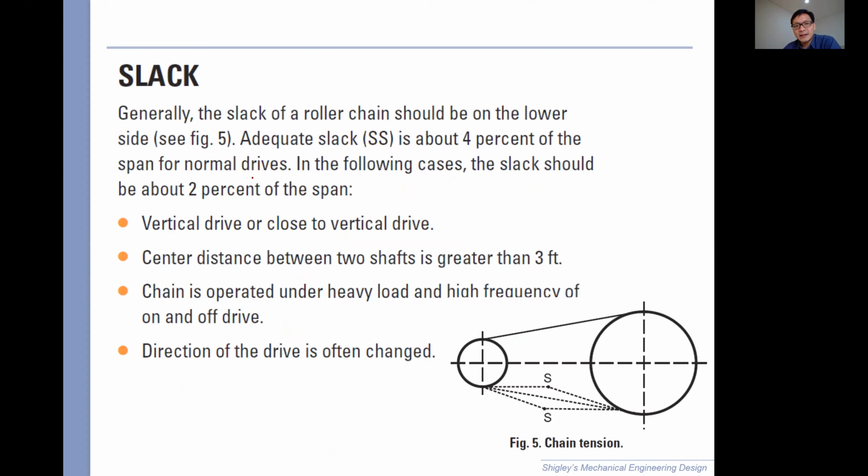There might be some slack on the roller chain, and this is tolerated up to a certain degree. This is the slack there. It should be 2% of the span. So S is 2% of the distance from end to end. Oh, so the slack has to be there, Pak? Definitely. If there isn't any, if you over tighten it, it can also wear out the chain prematurely. You're putting additional load that is not intended.